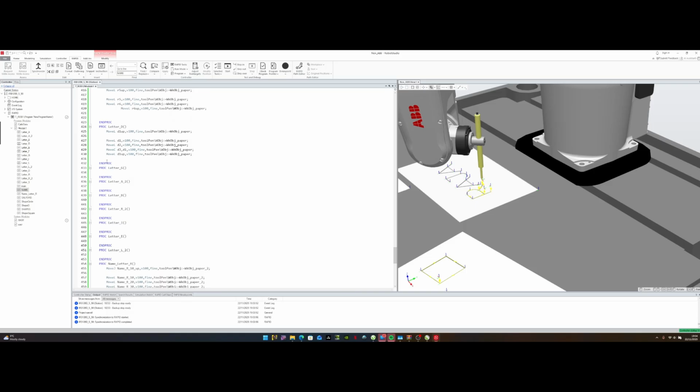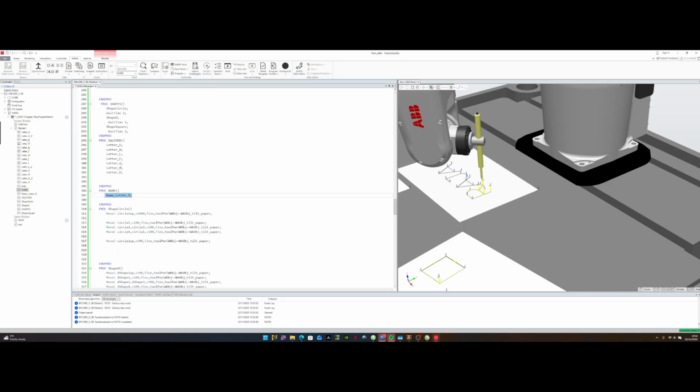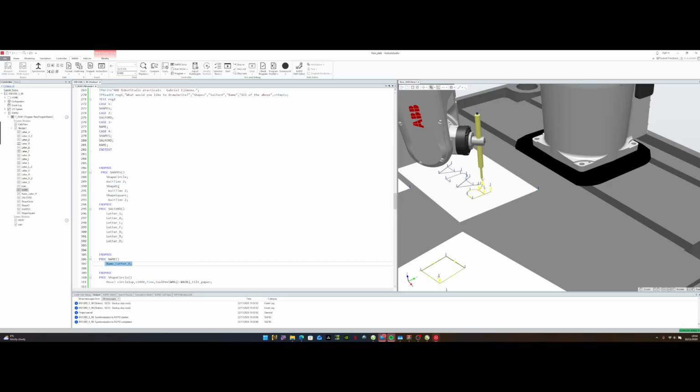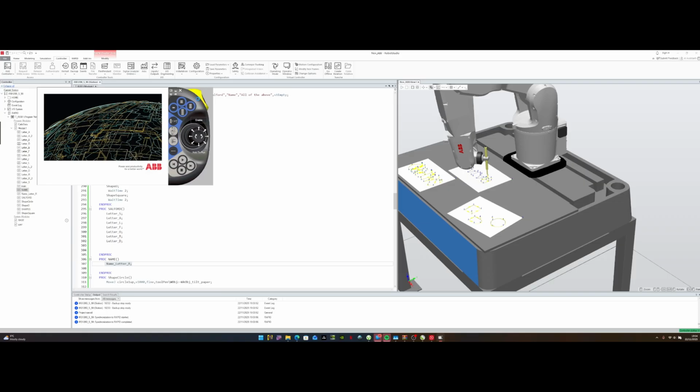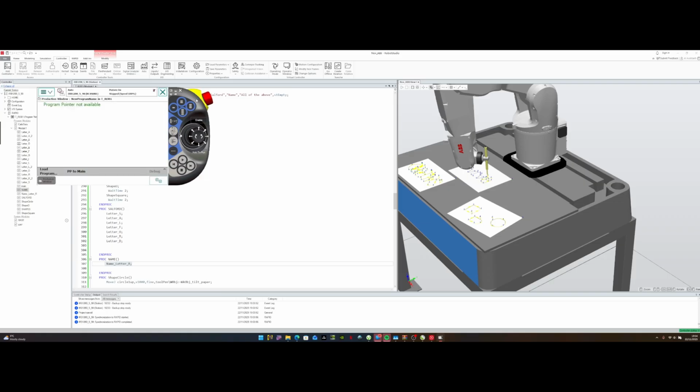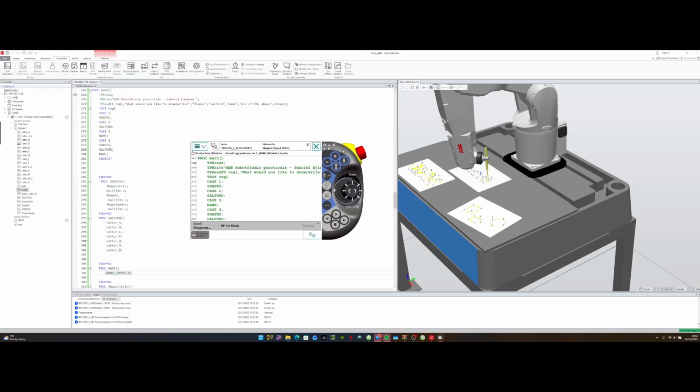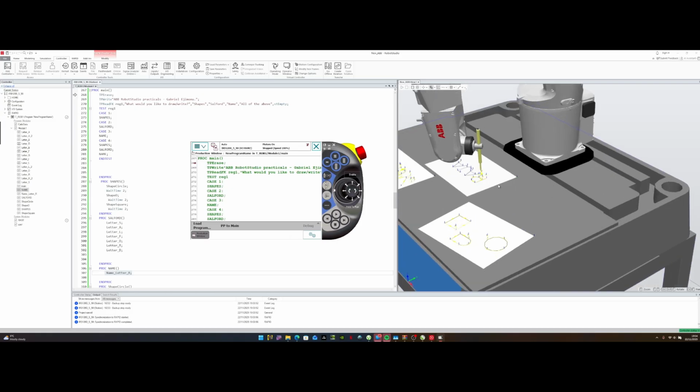These letters are still here, don't worry, we'll just ignore them for now. Letter R is here. You see the way I did it for Salford. Now let us simulate drawing this letter. Since we've added it to name, I can go over to controller, click on Flex Pendant to launch my Flex Pendant, because the Flex Pendant needs to be running. PP to main, yep. So we need to push the pointer to main, and I can just click play.